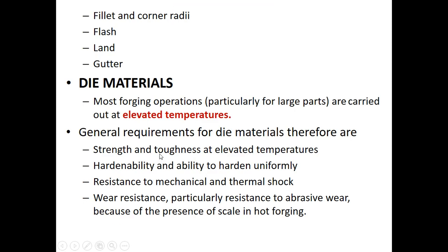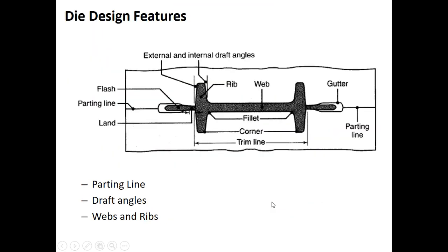Another feature is the gutter. You can see where the gutter is provided. It's a provision in the die design for the excess metal to escape without affecting the forging loads.